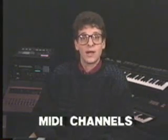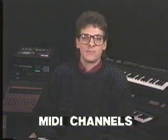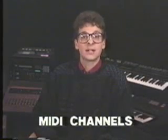Remember earlier we briefly mentioned that MIDI allows you to send and receive messages on different channels. In this way, you can control specific devices within a more sophisticated MIDI system. MIDI channels work in much the same way as television channels. For example, let's say you want to watch the evening news on Channel 2. There are also several other stations that broadcast their evening news, and your TV antenna picks up all of these stations. So you get up, you walk over, turn the TV on, and select Channel 2. Your TV ignores the programs on all other channels and just shows you the news on Channel 2.